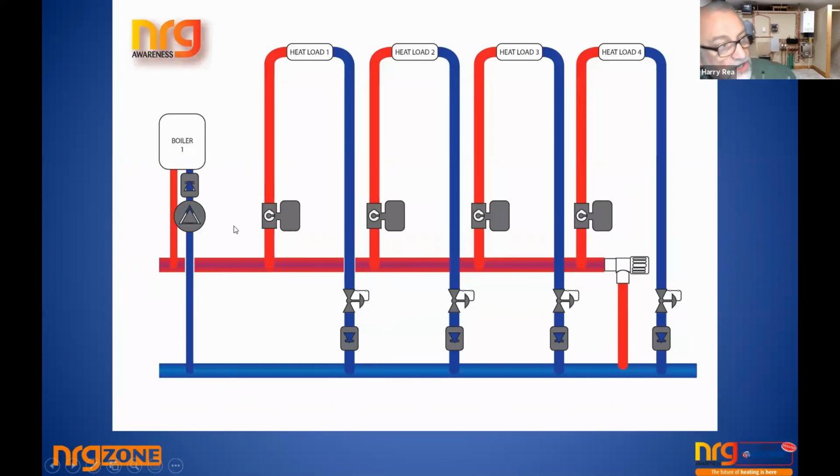So the only way it can turn off, how it does turn off, is the heat builds up in the boiler. It can't get out. And because it can't get out, it can't get at the return. If it can't get at the return, it can't satisfy the stat. So the boiler turns off based on inefficiency. It turns off because it has no reading of the system, because the only reading of the system it can get is if water comes through the zones and goes back.